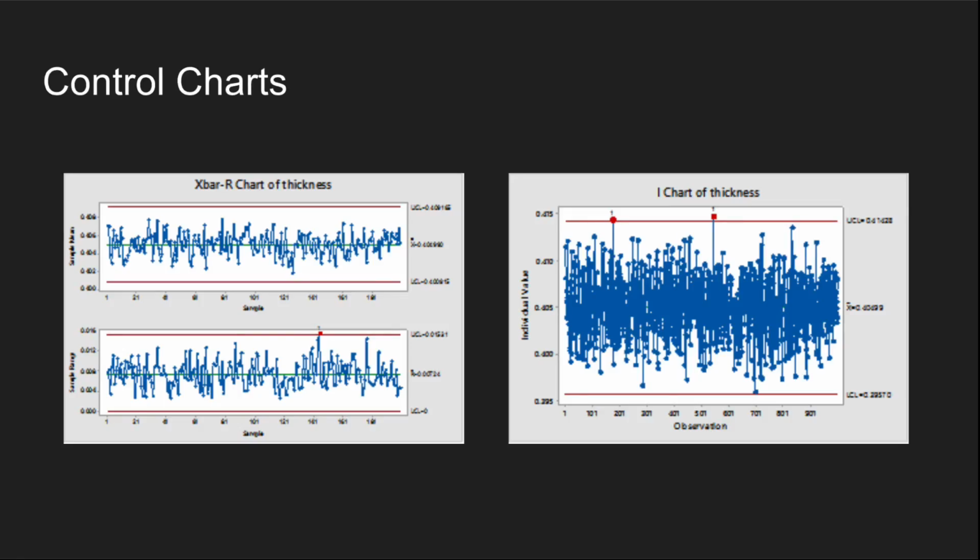The data for optical lens thickness parameters collection was given. A quality engineer at an automotive parts plant monitors the thickness of lenses. The engineer measures a shift's worth of production using subgroups of 5. The specification limits for the lens: target equals 0.405 inches, LSL equals 0.395 inches, and USL equals 0.415 inches. The quality characteristics of this dataset are variables of the individual product attributes.